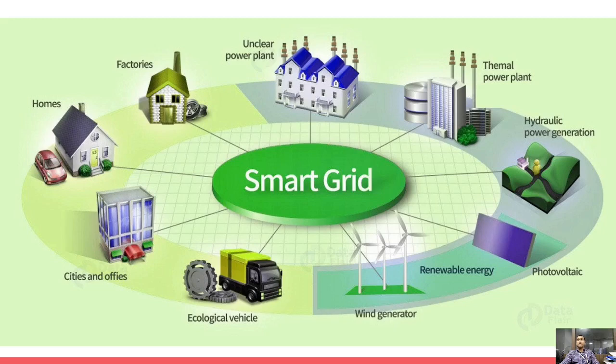Smart grid is basically a data communication network which is integrated with the electrical grid, and its job is to collect and analyze the data captured in near real time about the power transmission, distribution and consumption. We can consider the grid as a network that is used to deliver the electricity to our premises. Normally this grid should be balanced, like whatever power is being generated should be perfectly consumed. But whenever there is an overload or underload on the grid, it destabilizes the grid. So that's why we need to predict how much power is going to be consumed. This smart grid technology provides predictive information and recommendations to utilities, power transmission utilities or power production utilities, their suppliers and their consumers, on how to best manage power.